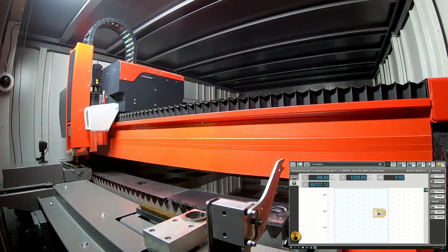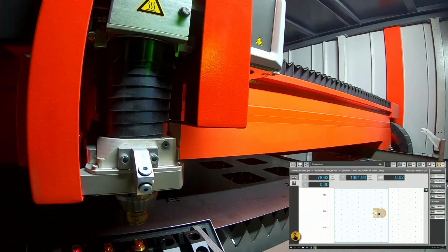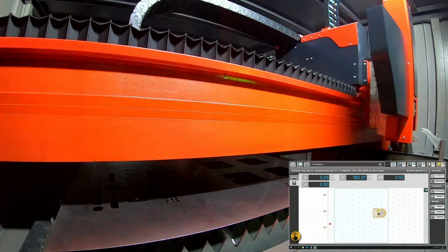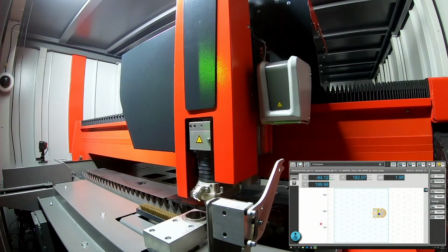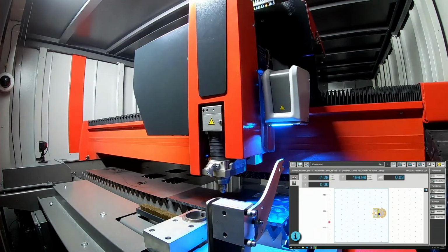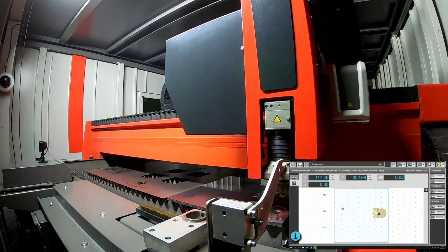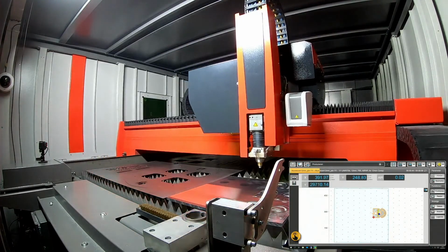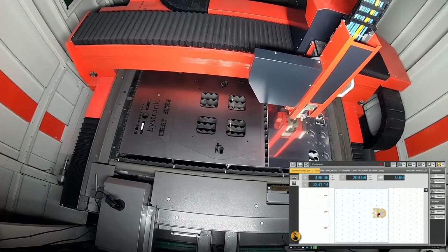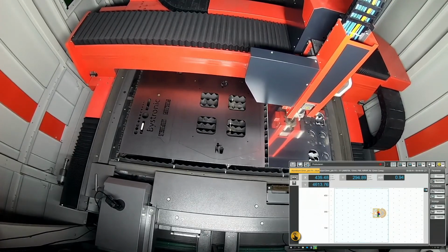So as well, we are changing the nozzle tip. So depending on the material, the gas, and the thickness, we have different nozzles. This machine here is equipped with 40 different nozzles. At the moment, we are doing calibration to make sure that the nozzle distance is always perfectly set. So now we have the detection eye, which is our camera system that detected the sheet within 6 seconds, which is actually a new feature on the BySmart fiber. So we're even faster and more proactive.